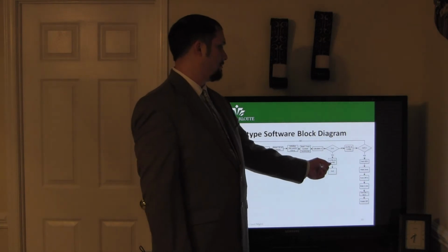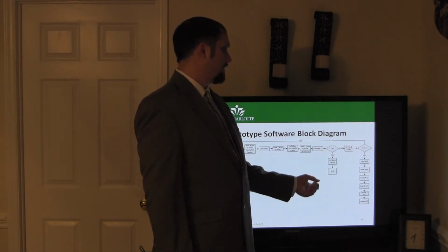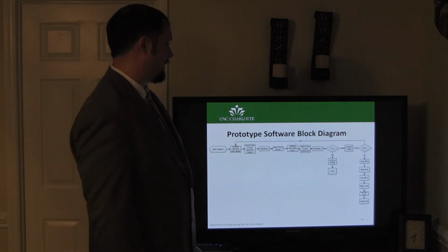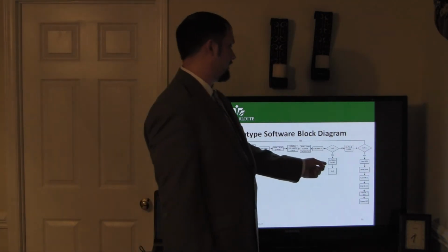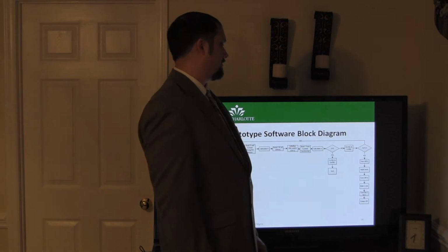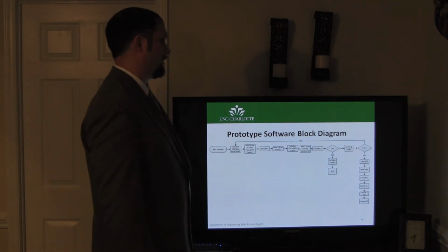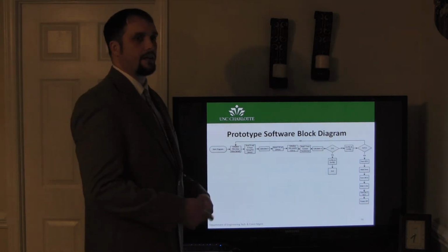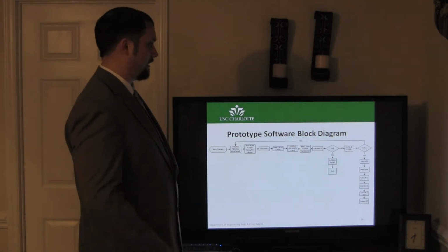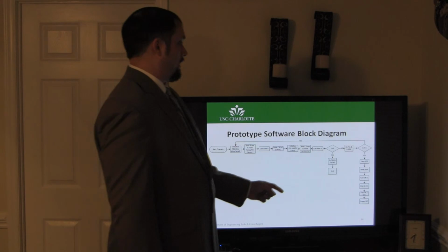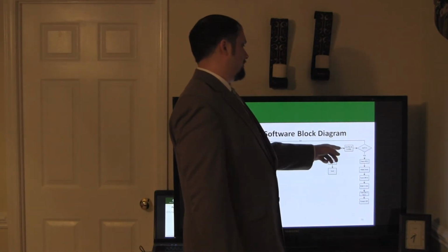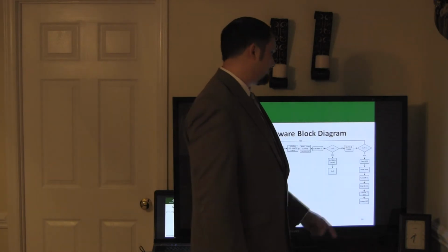In that case, we'll make PB1 the heat, and we'll make PB2 the drum, and we'll make X0. So we don't have to read that ADC no more. We'll turn off that loop. If not, if the current does not go below 2, then it continues on.